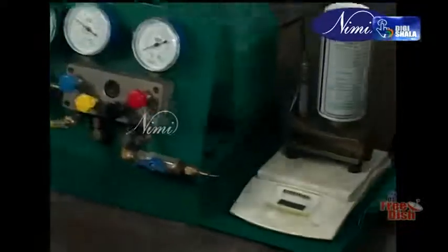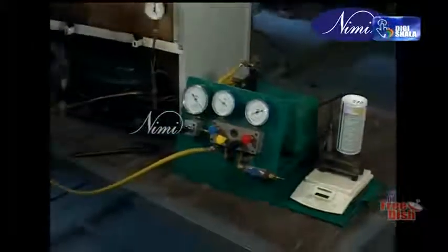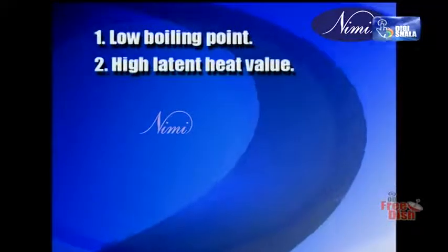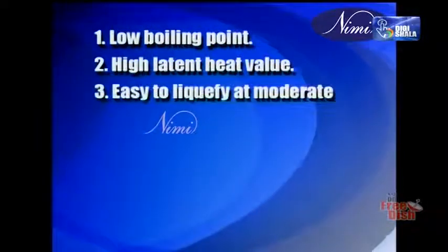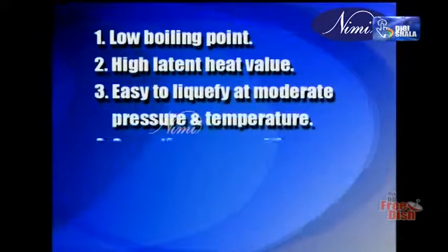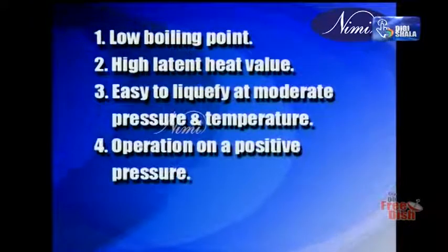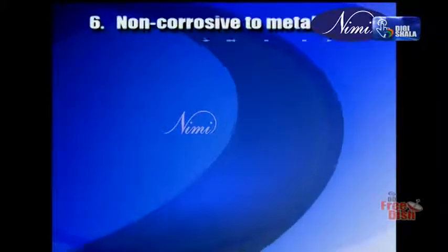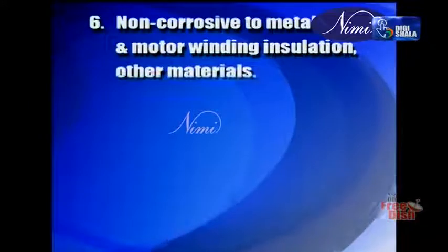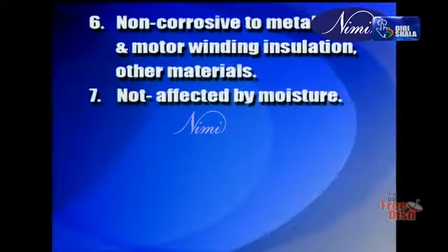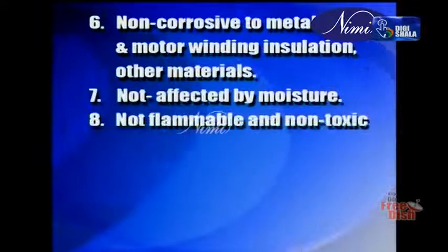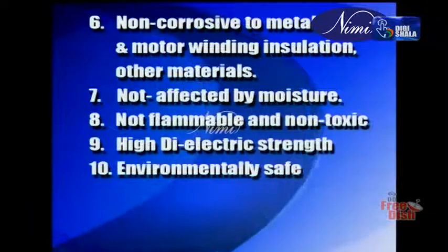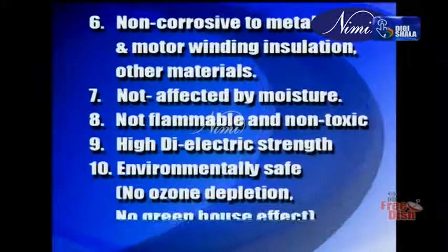The characteristics of a good refrigerant: low boiling point, high latent heat value, easy to liquefy at moderate pressure and temperature, operation on a positive pressure, mixes well with compressor oil, non-corrosive to metals, parts and motor winding insulation, other materials, not affected by moisture, not flammable and non-toxic, high dielectric strength, environmentally safe, no ozone depletion, no greenhouse effect.